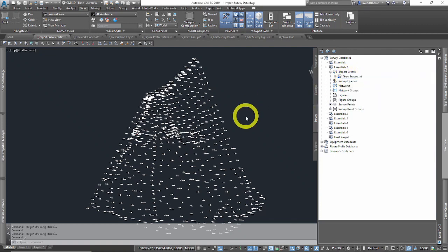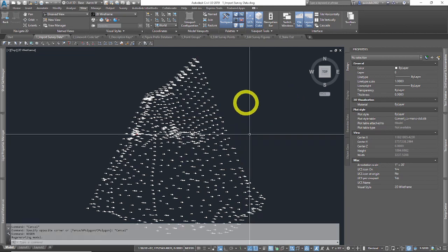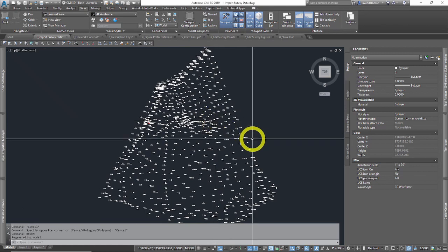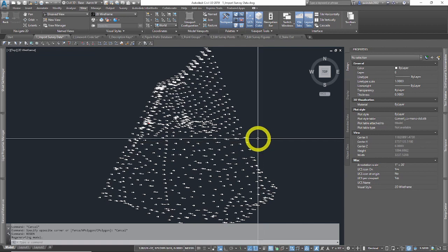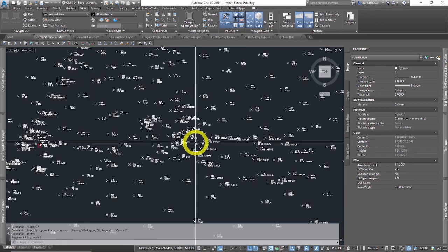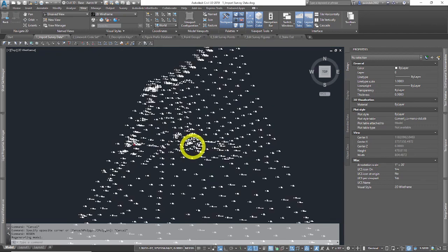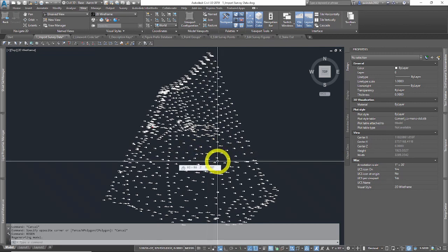Now I found them. I'm maybe typing in regenerate, R-E-G, or regen all, or regenerate, one of these two commands might have kicked AutoCAD in the butt and told it to regenerate this graphically. There's never a day when AutoCAD doesn't make weird errors like that, so just get used to it being a little glitchy on some of this stuff. And that is it on this example. So we just imported some survey data through the database. Mine looks a little different than the book example. You should have been able to do zoom extents and it brought it in just fine.